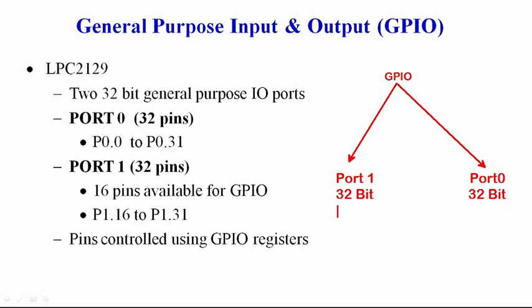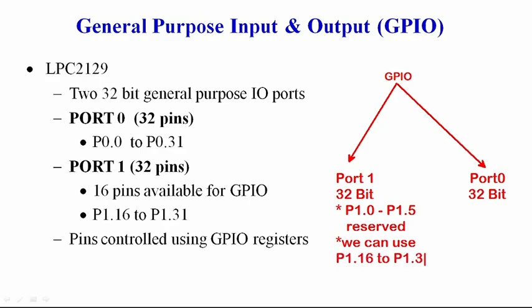Port 1 has some restrictions. In port 1, P1.0 to P1.15 are actually reserved for some system functionalities, and we can use P1.16 to P1.31.